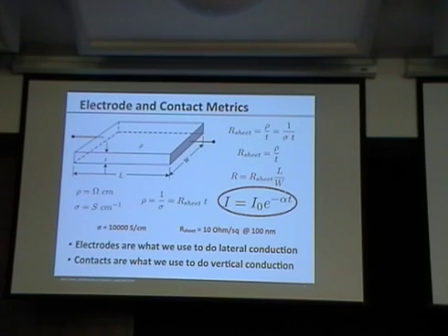And so I've been talking in terms of conductivity, which is the inverse of the resistivity. This slide outlines the relationship between the resistivity and the sheet resistance, which is what you spec. So why is sheet resistance the important number for you device makers? You get losses if your resistance is too high. That's right. I didn't put it up, but you know what the solar cell JV characteristic looks like. At high forward bias, if I have a lot of series resistance, what happens to that curve? It goes, yeah, which means that if it's bad enough, it can impact my fill factor.